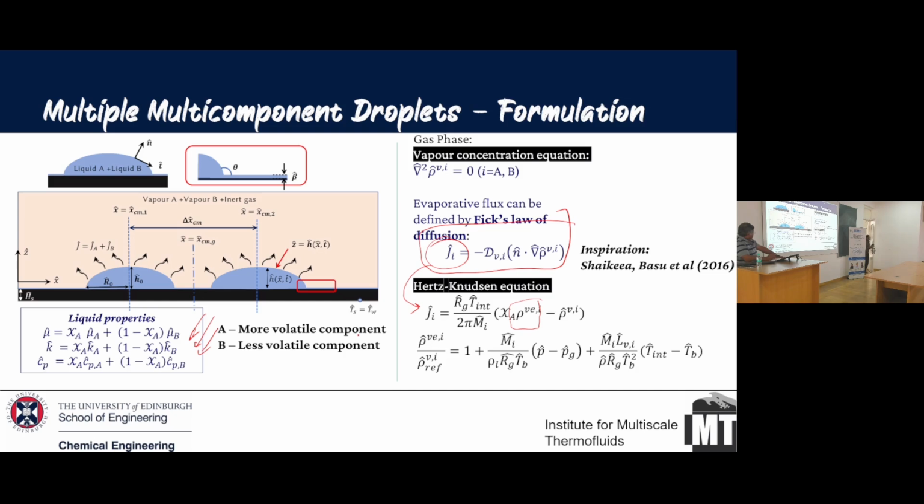Okay. So basically, the difference between what we have done before and what we have done here is that we are including the effect of the vapor phase. Okay? We are including the effect of vapor phase, but we are not including it completely. We call it the so-called 1.5-sided model. Okay? So when you have a two-sided model, you're accounting for the convection in the vapor phase, you're correcting for everything in total. That's what we do in DNS. But this is a 1.5-sided model. We are looking at vapor phase, but in a partial sense, just by the Laplace equation in the vapor phase.